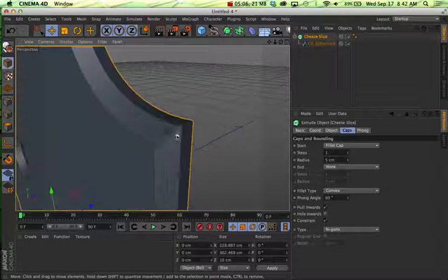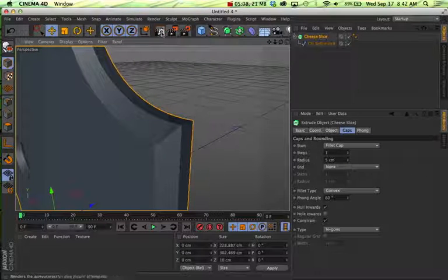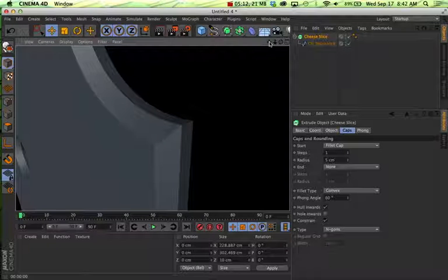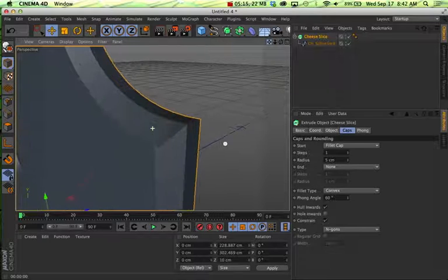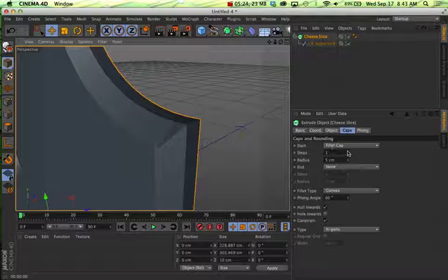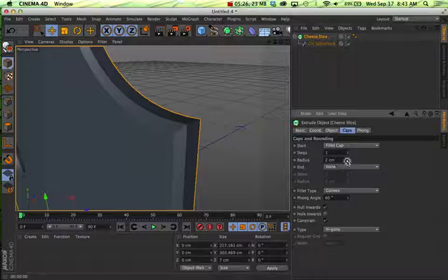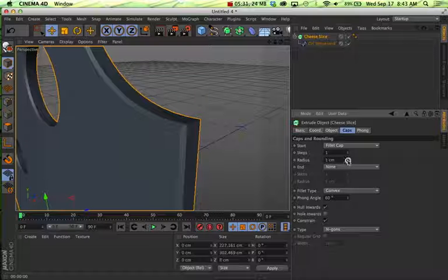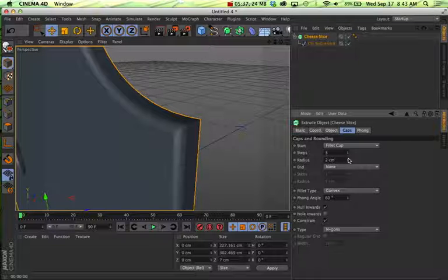Like here, if we zoom in, you can see those are causing some issues and they're overlapping. So what you have to do is make sure the size of your rounding, your fillet, is small enough that it doesn't start overlapping the whole width. So on this one, let's bring that radius down, and we can see now we've got a little bevel and it's working, but we also want to make it a little more rounded. We can do that, maybe 3 and 2.